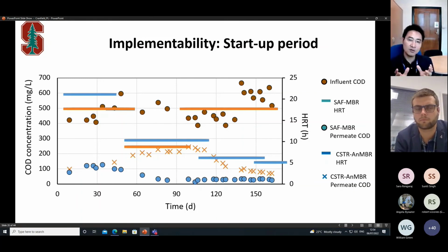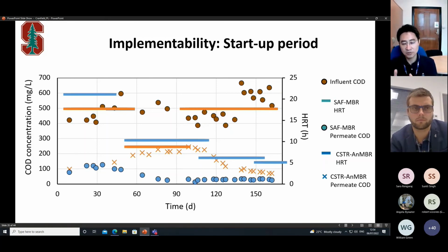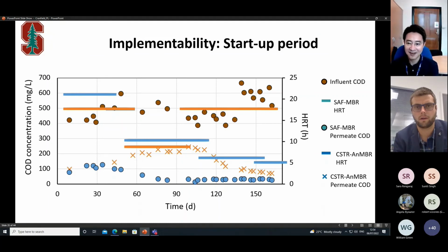But how you recover that methane in gas form and send it to CHP is also another problem. Hydrogen sulfide is also an issue. But we found that if we use a chemical reaction to recover phosphorus, some hydrogen sulfide can also be pulled down together with phosphorus. So that might be a new challenge ahead of us.